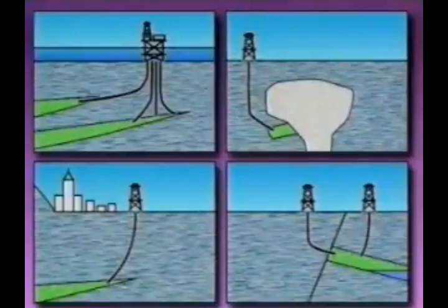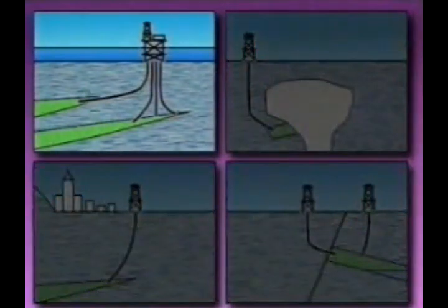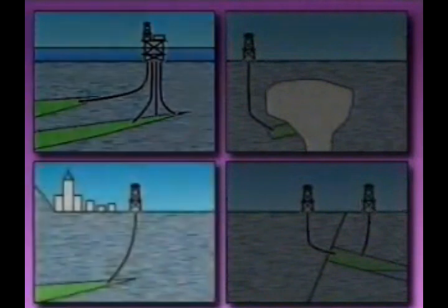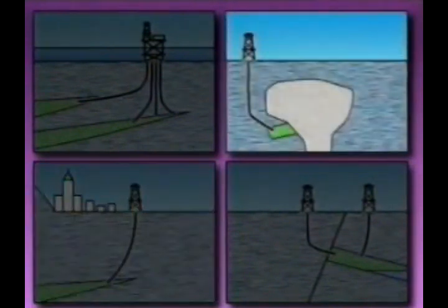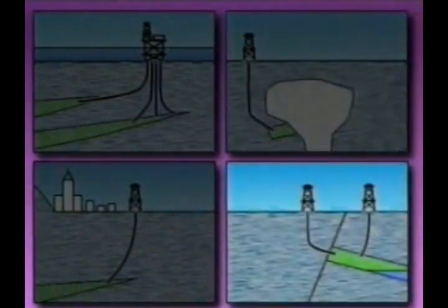Directional drilling is a way of reaching otherwise inaccessible targets. This makes it a valuable, even essential, reservoir management tool. Inaccessible targets might include offshore reservoirs, where we drill multiple wells from artificial structures, onshore reservoirs underlying urban developments, mountainous areas, or other surface obstacles, reservoirs underlying salt domes, which could cause innumerable drilling problems, and reservoirs associated with faults, where drilling vertically through steeply inclined fault planes could result in sheared casing if slippage occurs.